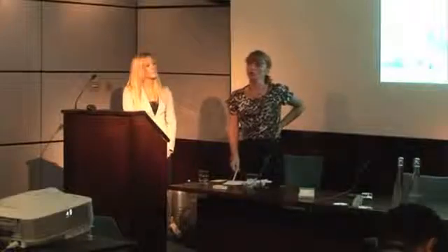What I would say on that is that it may be the case that your Revit model has the ceiling voids modelled, i.e. you have a dropped ceiling in there. Now, for the purposes of analysis, the question is, do you need those to be modelled as a separate zone or not? So do you need that ceiling void to be interrogable as a separate zone from the room? A situation where you might want to do that is where the ceiling void is active, so you have chilled beams or something going on in there that you want to know what the conditions are in that space.